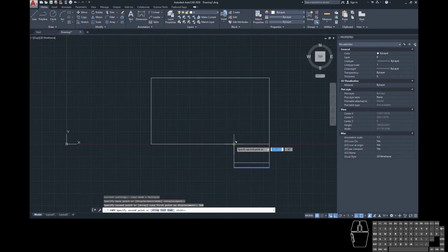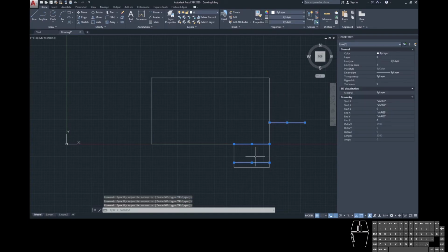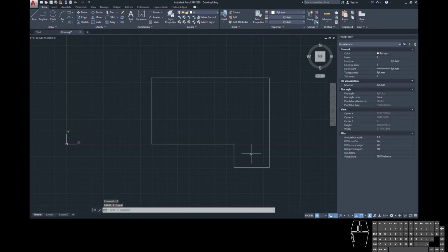It's also giving us the option to snap. So you can see here, that's precisely a continuation of that line because it has snapped to it. When you hover over other elements, so over here it's giving us a little triangle. That's snapping to a midpoint. That little cursor is then telling you midpoint. So you can snap to midpoints. And then enter or escape to end. And of course, we can delete those copies using the erase tool. E, shortcut.